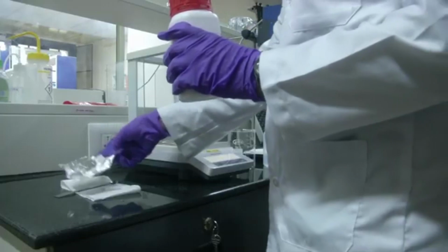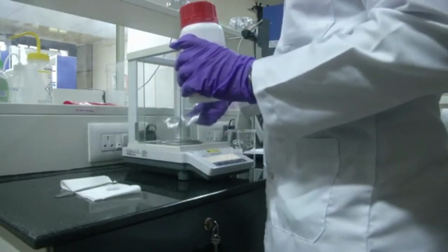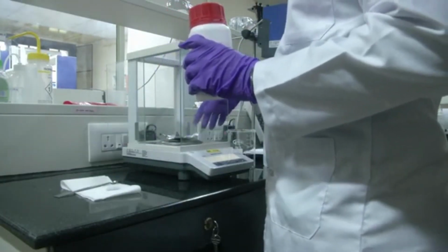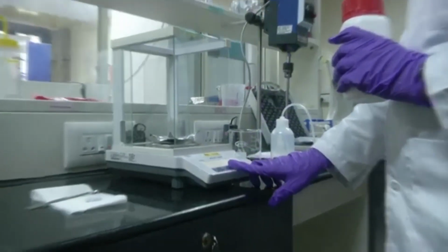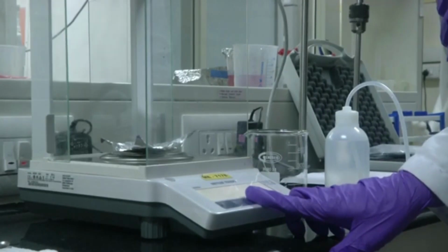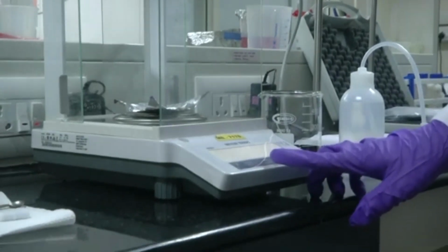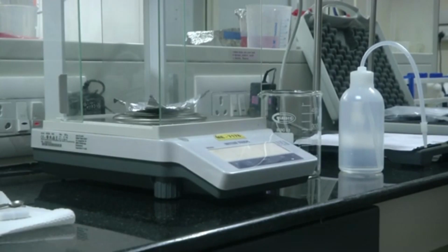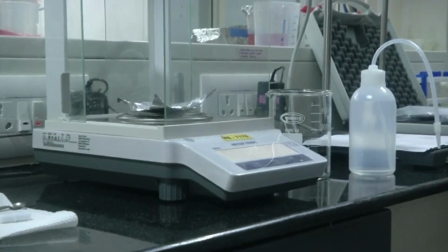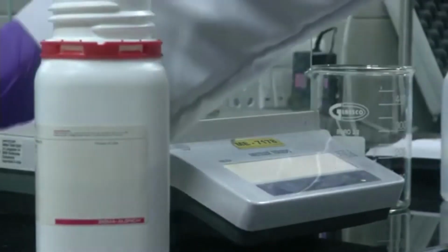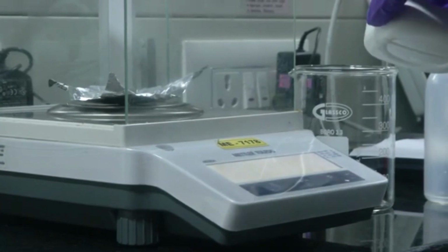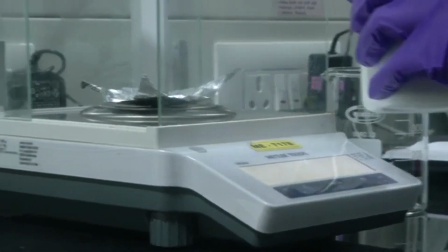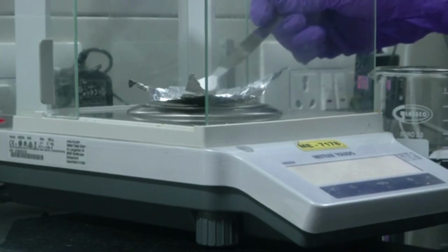In today's lab demonstration, we will be performing different rheological experiments using a solution of PEO or polyethylene oxide. Before we begin the experiment, we need to prepare a solution of PEO. The molecular weight of PEO we are using for this experiment is 5 million grams per mole. This is a viscosity averaged weight and is provided by the supplier. The polydispersity index of this powder is 1.14 to 1.37.